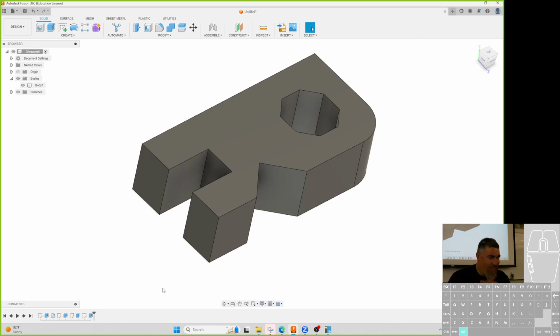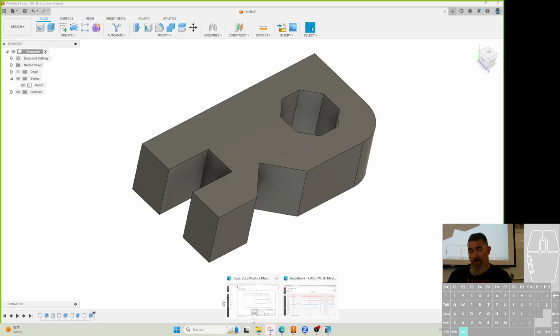Very nice, Ron. All right, so that's when if we have things we can draw as a square, we want to just add fillets to it. It makes it easy. It makes it easy to change. We have lots of options on how we do that. But sometimes we need to sketch the radius in there, right? What kind of gives us the rule of when we need to sketch the radius? When we would need to include the radius on the sketch? Any ideas? I said it earlier.